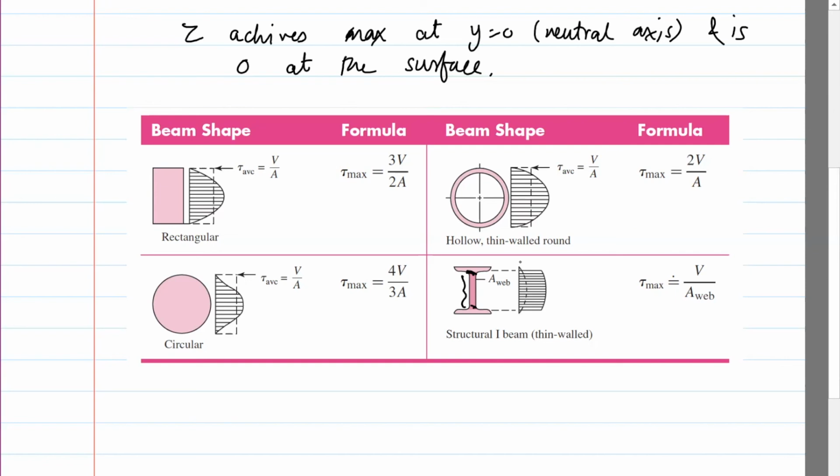So you see that there's sort of a disadvantage of having an I-beam when it comes to shear stress, because the shear stress is kind of high over the complete vertical part of the I-beam. And then you can obviously do these things for the moment, and that's where a design problem happens, right? When you have two competing stresses, which stress dominates, and whichever stress dominates is the one which you'll be using to design. So that's a question which will come today in another question.